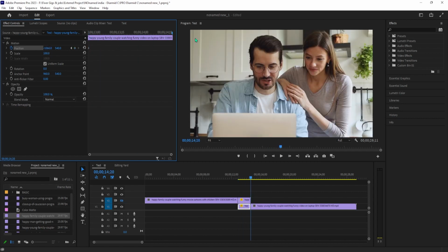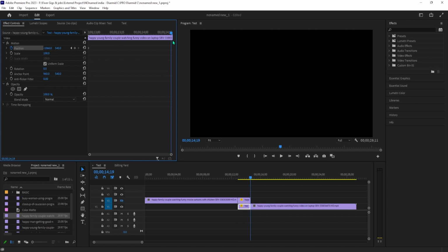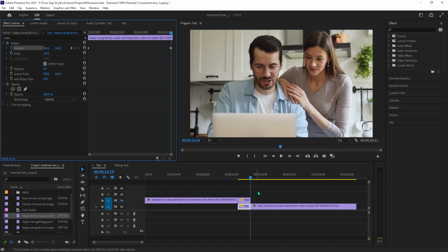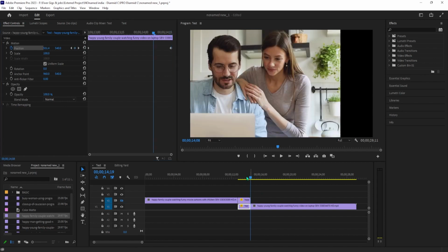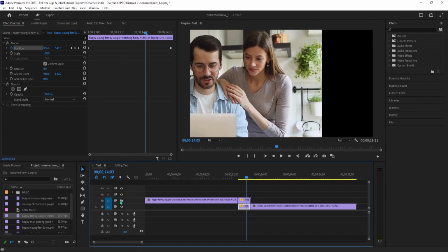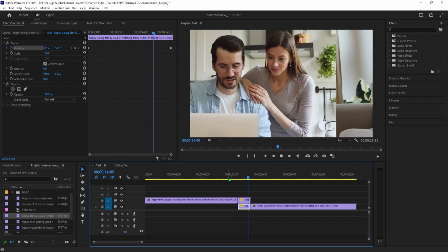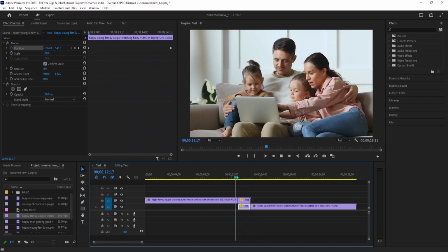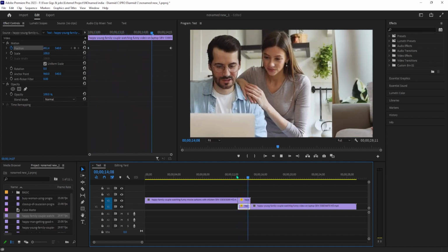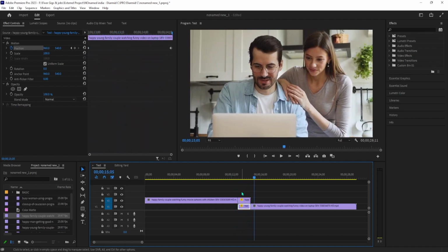Next, move the playhead to near the end of your clip. Once again, I'll leave mine about 1 frame from the edge, which will make our lives easier later on when we're selecting keyframes. Then click the Position's Reset Parameter button to create a keyframe to set the video back to its original position. Okay, now let's turn our AI toggle back on for our top video and check out the result. Voila! It's a simple push transition, but unlike the one in Effects, we'll be able to smooth it out.